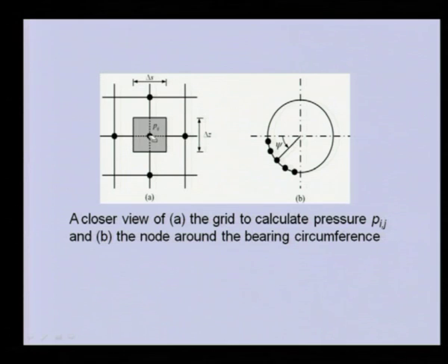That we will see in the procedure, but let us see this particular point which is there in the unwrapped position. If you want to see that particular point in the bearing, this is the point, and the angular position of it we are representing by psi. So this particular pressure, if we multiply by the area, we will get the force it is exerting onto this bearing, because this is the pressure at this point.